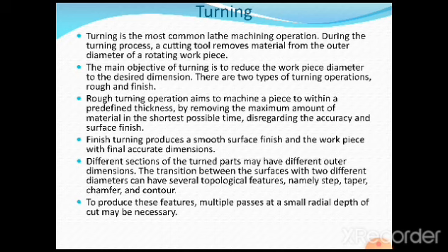See, what we do is a very simple understanding. In case of rough turning, we give more depth of cut and we are not bothered about the surface finish or the dimensions. Why do we give more depth of cut at the beginning? Because if I want to reduce, taking the same example, from 25 to 20 millimeters, I have to reduce it by 5 millimeters. So directly at the beginning I can go for 2 millimeters. If I go for a 3 millimeters total depth of cut, then what happens? You are going to reduce from 25 to 23.